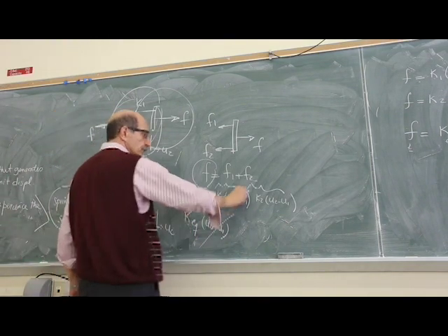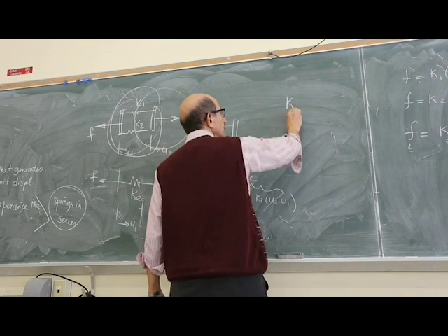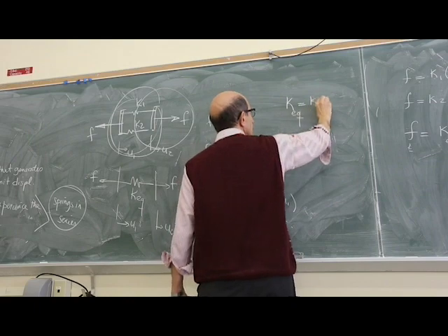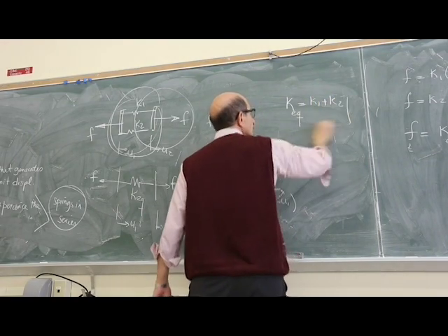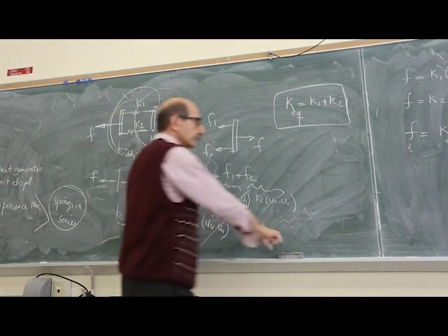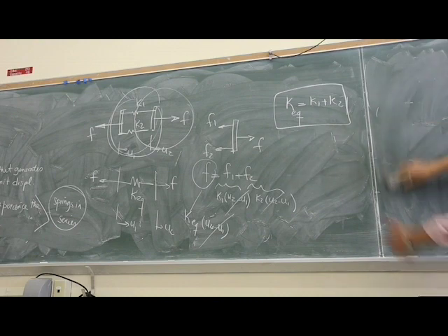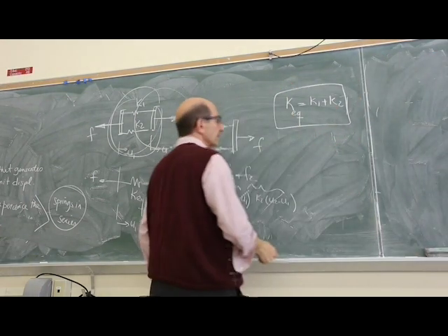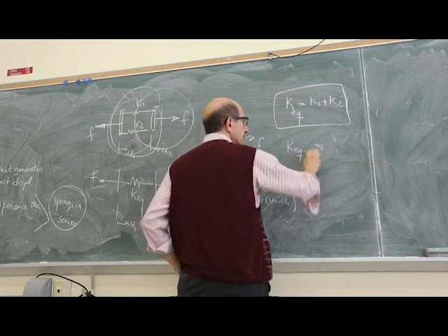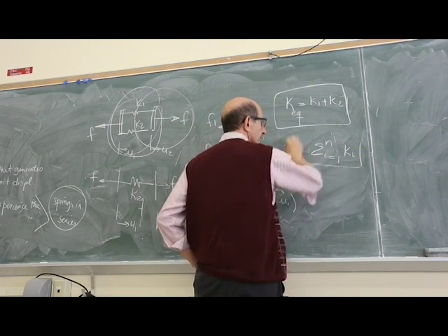So as you can see, these from the two sides cancel out. So if the springs are in parallel, the total stiffness would be the summation of them. Okay? And of course, again, if you have a large number all in parallel, then in general, K equivalent would be simply the sum for i from 1 to N of Ki.